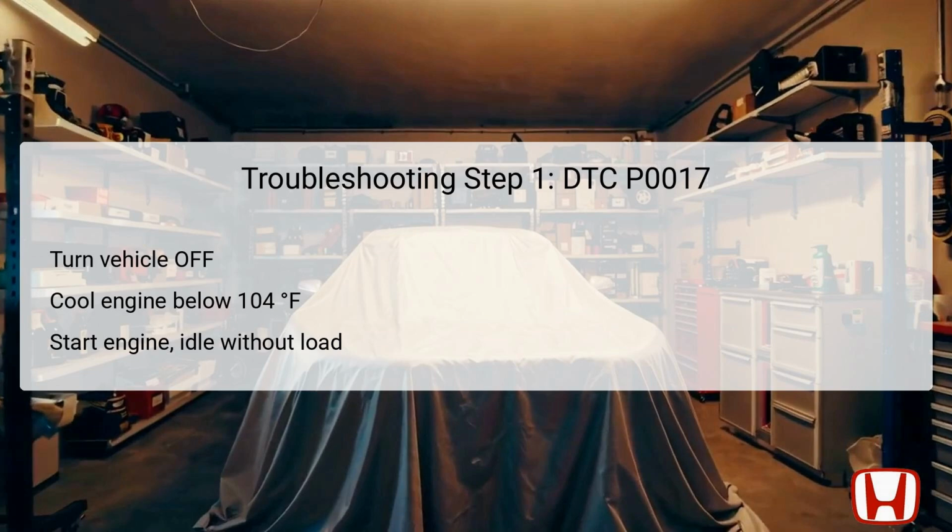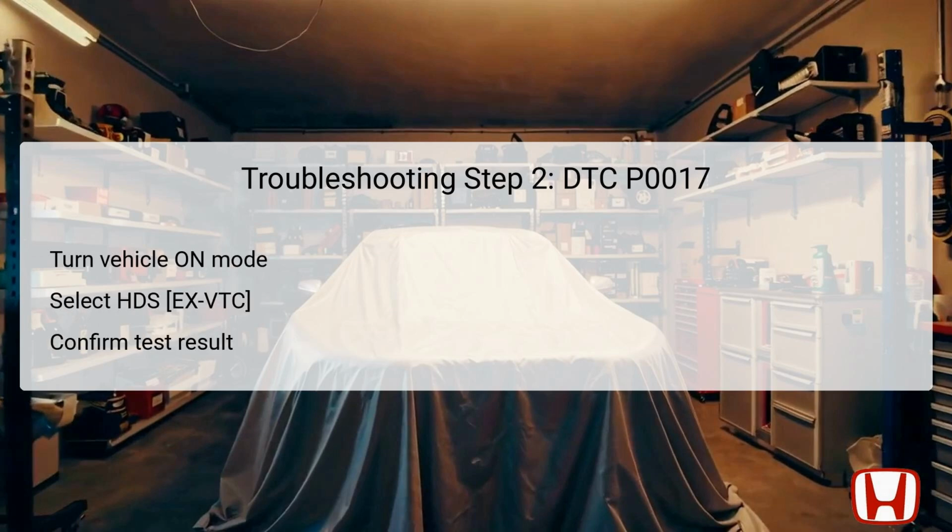Step 2 requires turning the vehicle to the on mode without starting the engine. This allows the vehicle's diagnostic system to perform a self-check. Next, using the Honda Diagnostic System, HDS, select EX-VTC, which stands for the Exhaust Variable Timing Control. It is essential for controlling the camshaft phasing for improved performance and efficiency.